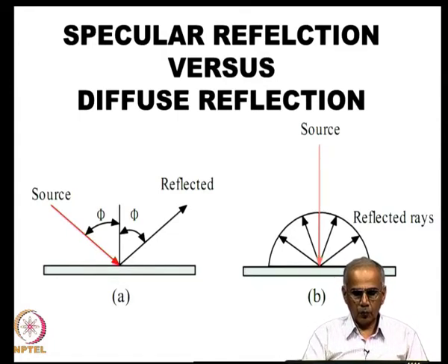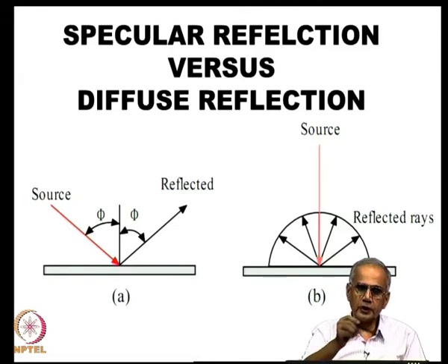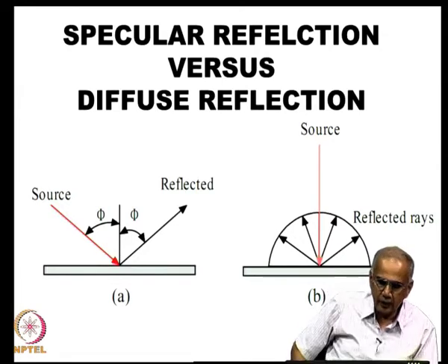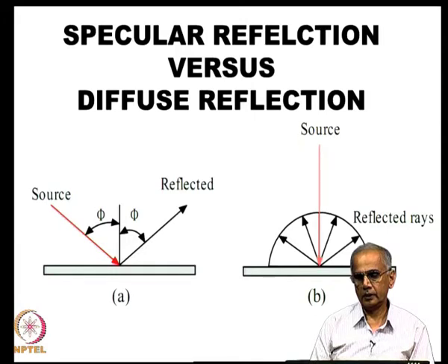Now, when a surface reflects like a mirror, it is very important to know where the photon came from. So, you have to trace the photon's history through the enclosure. This is called ray tracing, and this methodology is now getting more and more popular, but you can imagine that it is quite laborious and tedious.